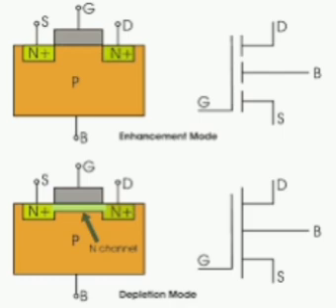In case of reverse bias, junction capacitance is the same as transition capacitance Ct. In reverse bias diode, transition capacitance varies as Ct directly proportional to V power minus n, where V means applied reverse voltage, n means 1 by 2 for step graded diode, P plus N or P N plus, equal to 1 by 3 for linear graded diode, and equal to 1 by 2.5 for diffused PN junction diode.